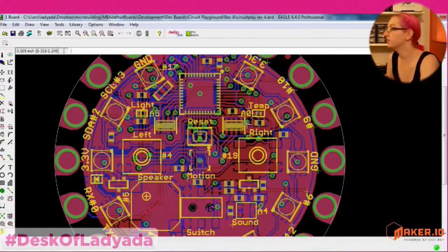I couldn't actually fit 0603 resistors. I used a resistor pack. Check out resistor packs, capacitor packs. I didn't used to use them, but for about the same cost of 4 components, you get 1 component, and you pick and place it at once, and it works great.